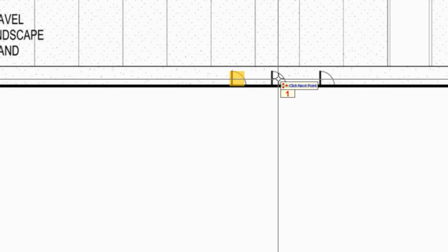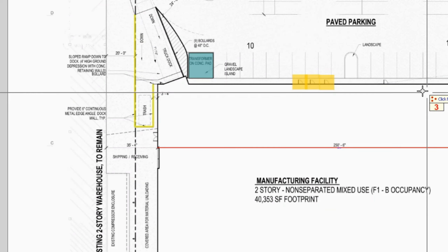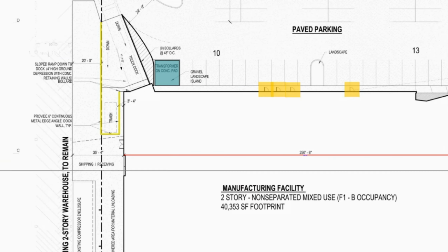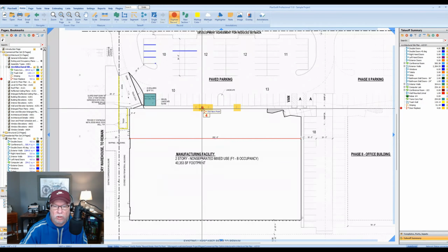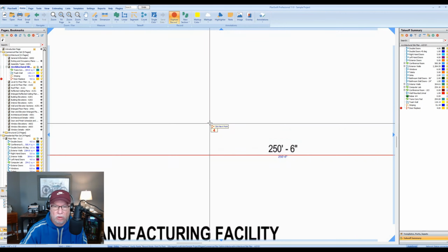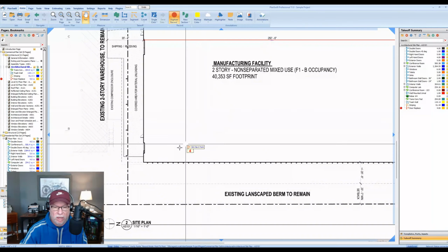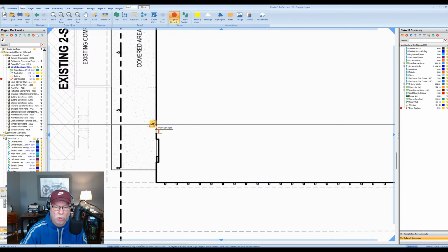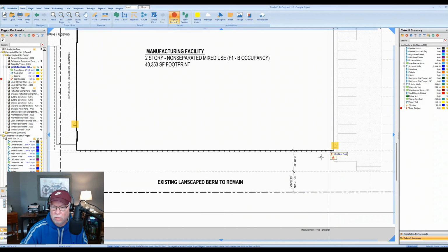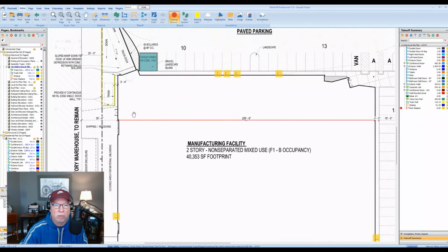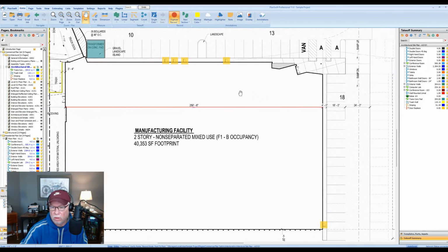And I just start counting. There's my little squares. And it always keeps them, so even if you zoom out, you can see those squares. And that's how the scaled function works. If you didn't want to see it blown up like that, you would click on that scaled button. So there are the doors I need to replace, just the man doors. And I hit stop up here, or I hit escape. And off the side here it says door replace 6.